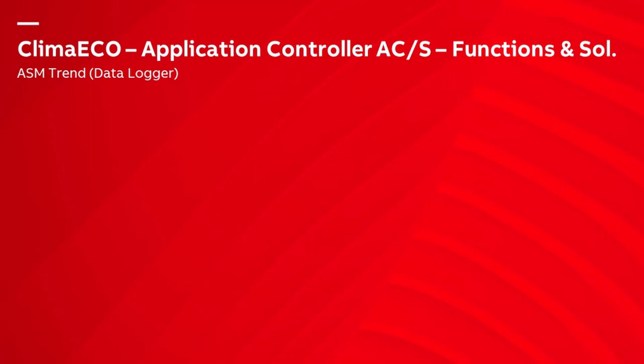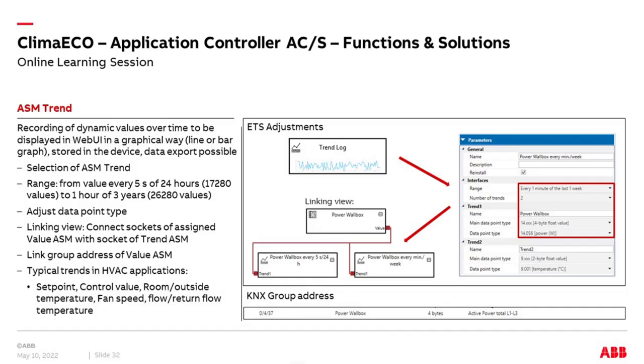Yeah, let's come to this ASM trend. It's a good module to show a bit in practice. In brackets, I've written here data logger. It's a kind of data logger. And how do you do this? It's again an ASM you select. Then you adjust a bit in the parameters. Remember the resolution, how often you would like to record, and how many of these trends you would like to have in one view later.